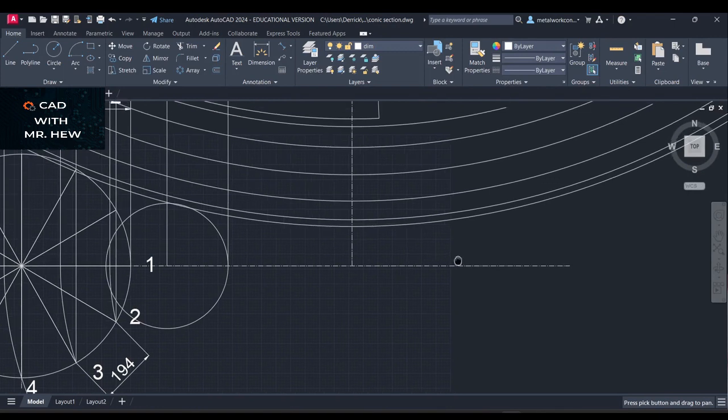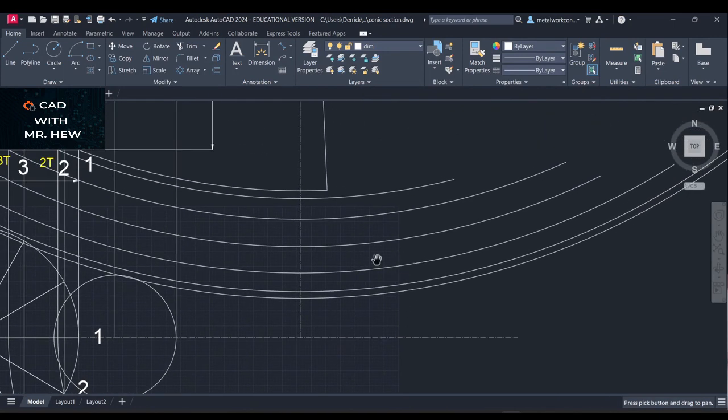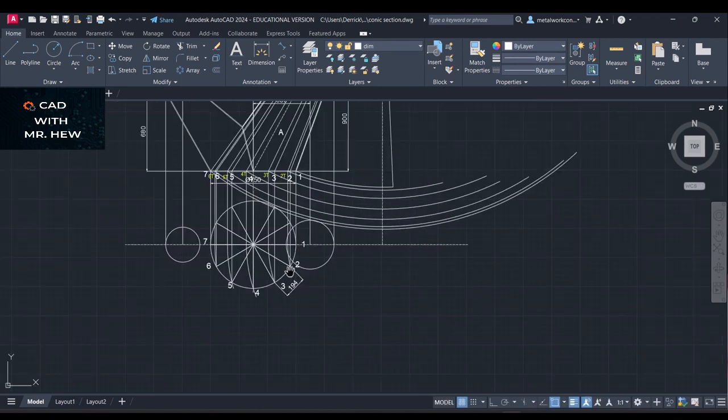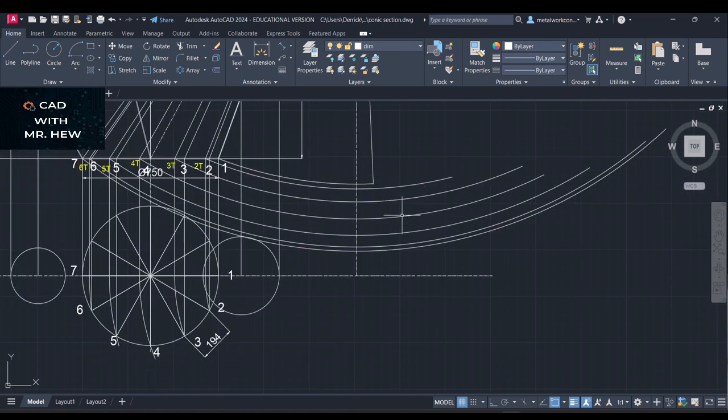So what we need to do is draw circles of radius 194. What we'll be doing, we'll be setting out this distance along the base of the development. All right, so let me show you what I'm talking about. All right, so I'm going to draw a circle to represent my arc. All right, so I've marked the arc from this point 194 intersect the true length line coming around from T2 there. Okay, so from this point, right, I need 194.